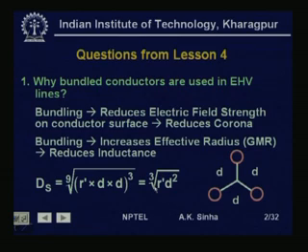This is much larger than r', which is used when a single conductor is used, and therefore bundling helps in reducing the inductance as it increases the effective radius.